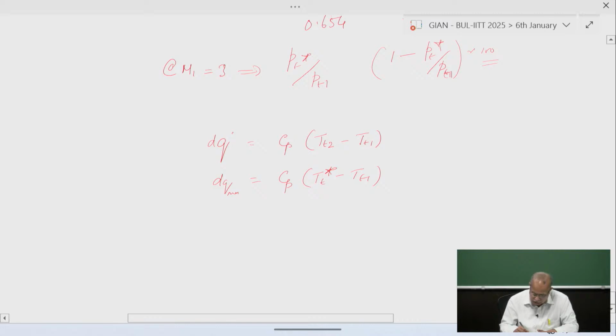So which means we need to write the full equation. This is the amount of fuel that is required of that calorific value, which is 122 megajoule per kg because of the hydrogen. No efficiency information is given on the combustor, so we'll just assume that to be 100%, is equal to m dot O, mass of air, Cp Tt star minus Tt1.